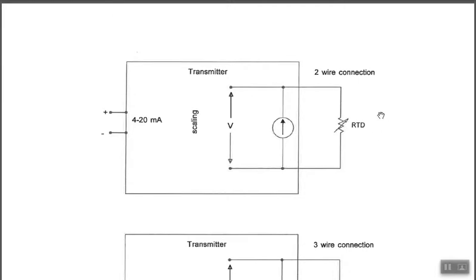So to trace it through, as temperature varies, the resistance of the metal varies. As the resistance here varies, current we're holding constant. So with Ohm's law, of course, current's not going to change because we're holding that with a constant current source. And then your varying resistance with constant current gets you your varying voltage, and that represents the temperature.